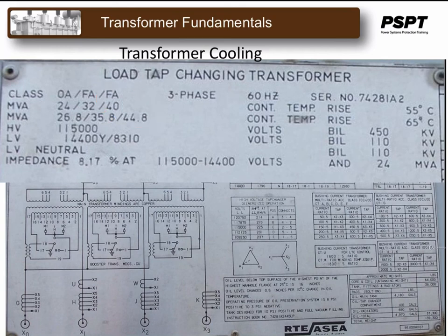Again, these fans should be turned on automatically. However, if they are watched by an operator, these temperatures will have to be adhered to. And again, ultimately, there is relaying in the transformer that will take it out if the temperatures are exceeded for a longer period of time.